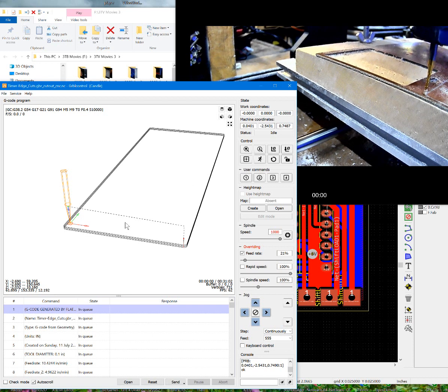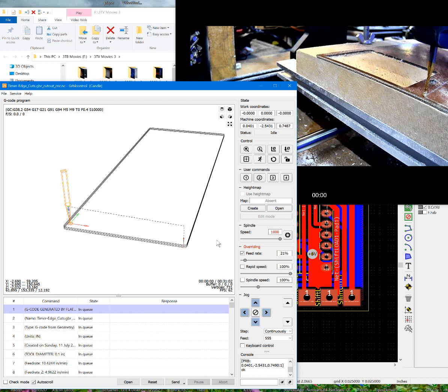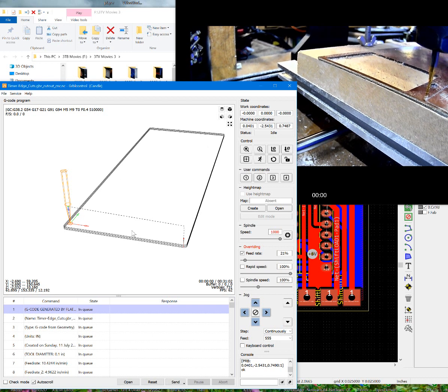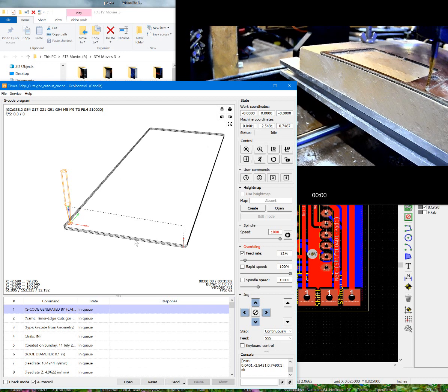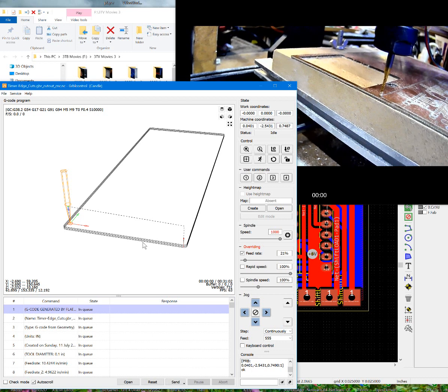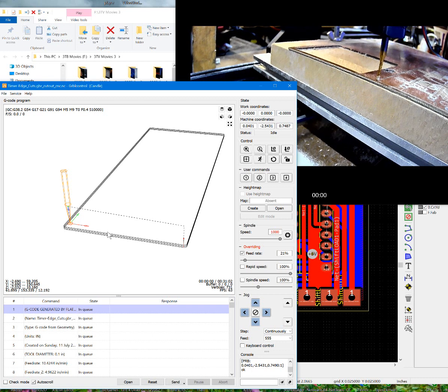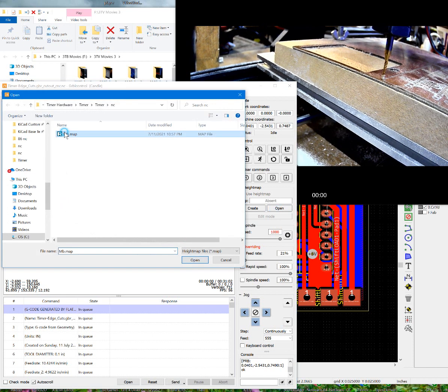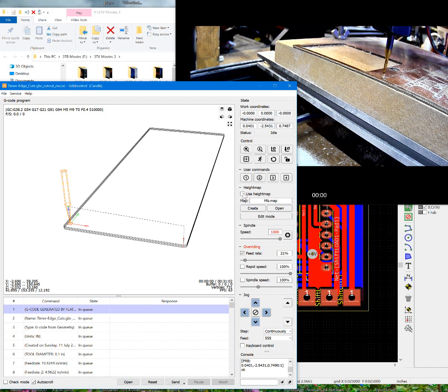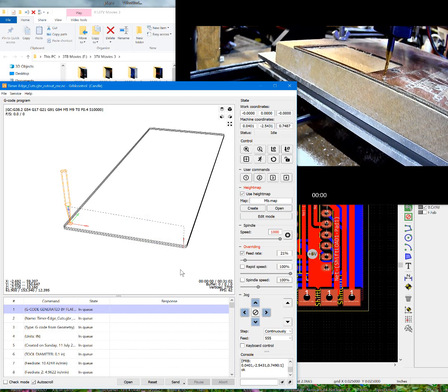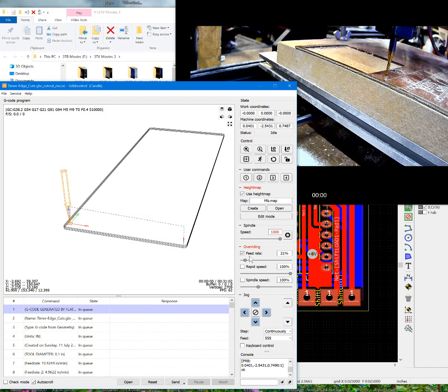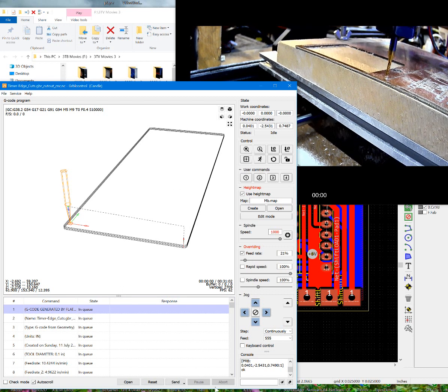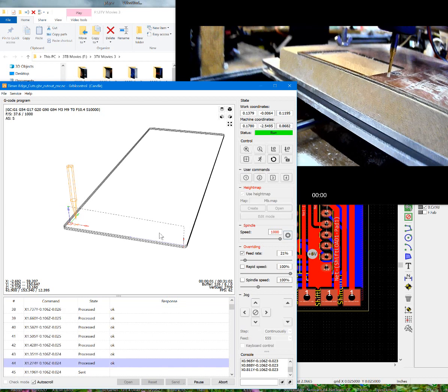Now if you're doing a smaller board, you can experiment with it, but honestly, something that takes over 2 hours to route the traces, I don't suggest you experiment with that very much, unless you don't value your time as much as I do. But anyway, I gotta remember to open the map file, and remember to use height map. Since we got our feed rate set, our tool loaded and zeroed, we're ready to actually send it to the unit.